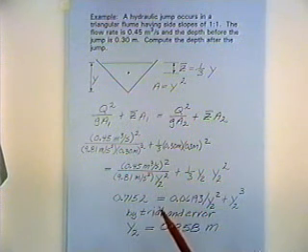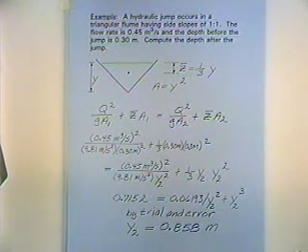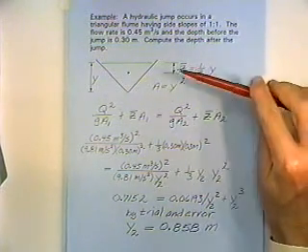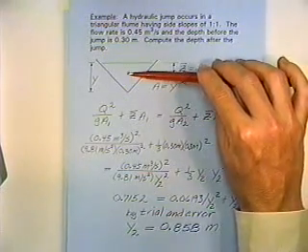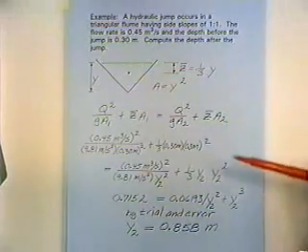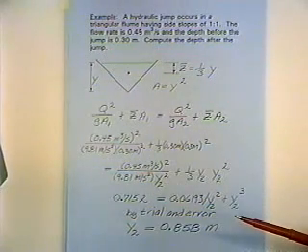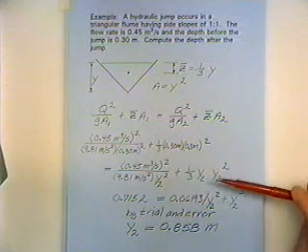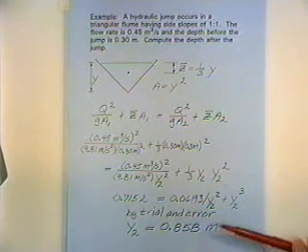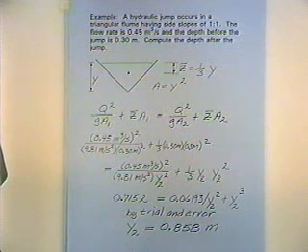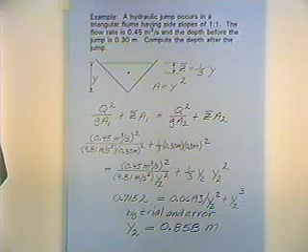The acceleration of gravity is a constant. We can plug that in. The area of this triangle is y squared. The z bar, the distance from the water surface to the centroid of the area, is 1/3 y. From that geometry, we can plug in for z bar and the area. We know everything except the depth, and then we can solve for the depth. Given the depth before the jump being 0.3 meters, the depth after the jump is 0.858 meters.